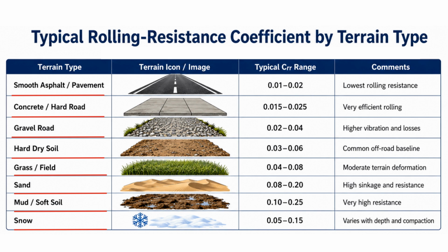These values are approximate and must be adjusted for tyre type, inflation pressure, wheel load, speed, and actual terrain condition. The formula remains resistance force equals CRR multiplied by the normal load. Therefore, a higher coefficient directly increases the tractive force and power required from the vehicle.